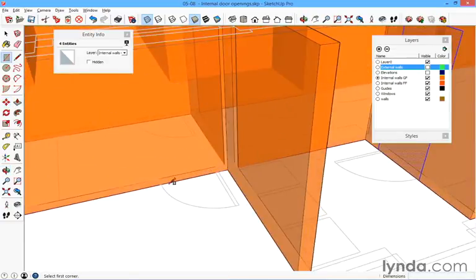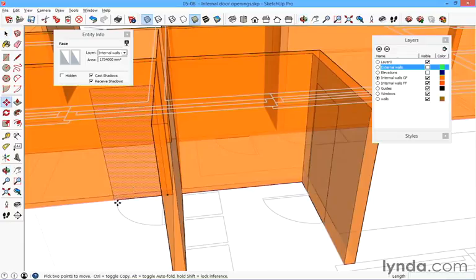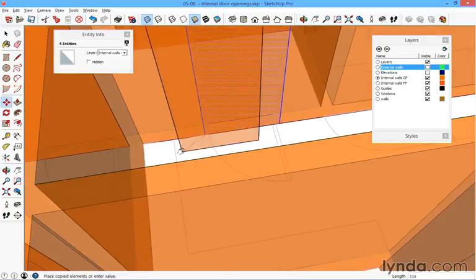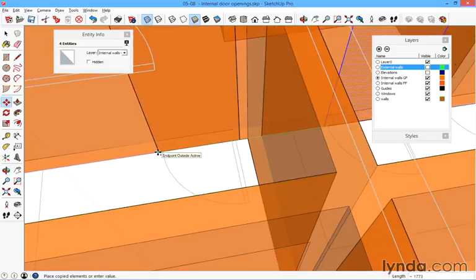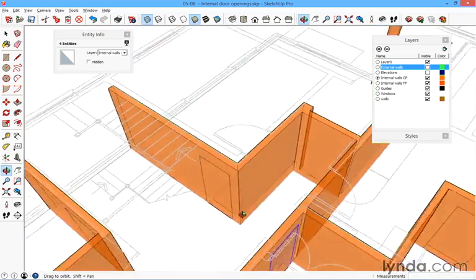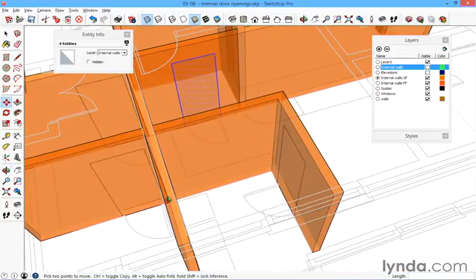The other ones, we'll just knock up another one in this plane. So again, rectangle tool, click, and then once you've got that point, lock out, and then you can move up to this point. And once you've got this in position, then we can select that, M for move, tap the control key, and then we can come around and position these there. There's that one, there's that one, and I think, oh, that wasn't copied, apologies. There's that one, and I think that's it.